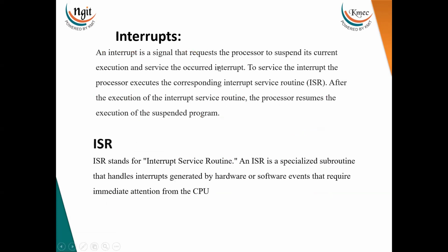An interrupt is a signal that requests the processor to suspend its current execution and receive and service the occurred interrupt. To service the interrupt, the processor executes the corresponding interrupt service routine. After the execution of the interrupt service routine, the processor resumes the execution of the suspended program.